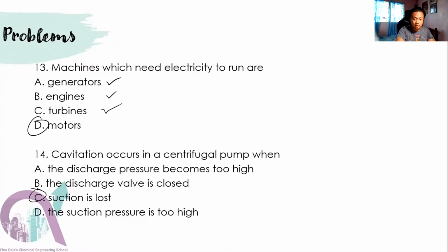Discharge pressure becomes too high, no. Discharge valve is closed, no, there will be no flow. The suction pressure is too high, not necessarily. Cavitation occurs when the pressure inside the pump goes below the saturated pressure or the vapor pressure.